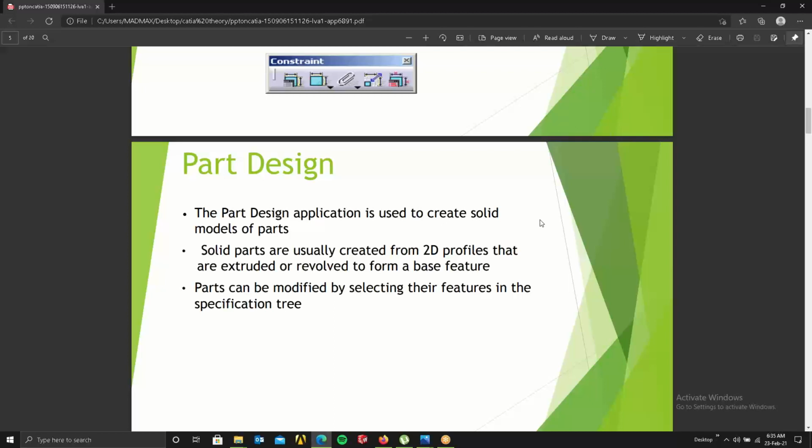Like if it's in an angle. Okay, if it's an angle, then I have to give 30-degree angle in one place, and I have to give 30-degree angle in another place. Again like two to three places I have to give it. So better than that, if they are like facing each other, what I'll do is I'll give 30-degree angle for one, the other part I'll just mirror it. Like I'll just give parallel constraint. So what is happening is, I don't have to give 30-degree angle here. I just have to give one single constraint, and the side will be done.